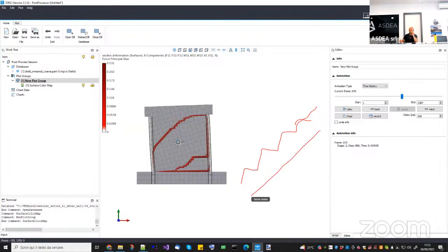Even if the equivalent homogeneous strength is the same, and the amount of dissipated energy is the same, the crack will develop much faster because the mesh itself is more able to bend than in reality, okay? I don't know if this concept is clear, but you make everything more homogeneous than it is in reality.